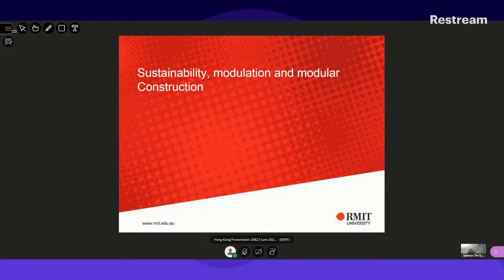Most of the students are just joining a couple of internal walls and then using the edge of the shear walls, or the dark colored walls shown, assuming that they are perfect walls, very smooth and can be painted. Once painted, it looks very good. It is not. So on those walls, there is a different kind of cladding that you have to use. Of course, it is not a dry wall per se, but it is a cladding around those walls, because you can't assume that it has a pre-stressed concrete finish.